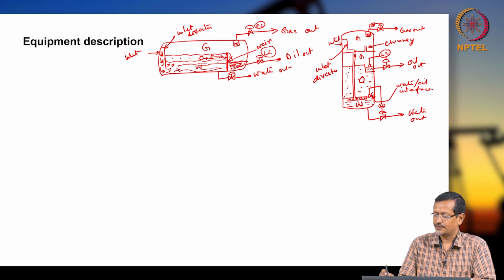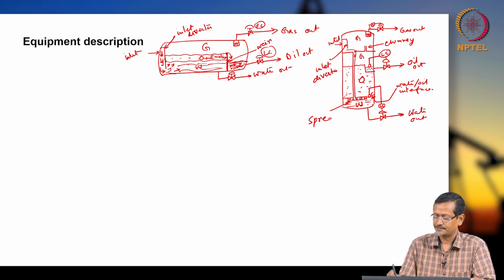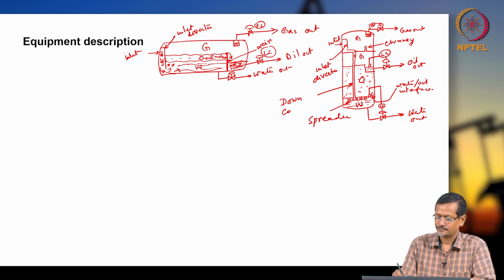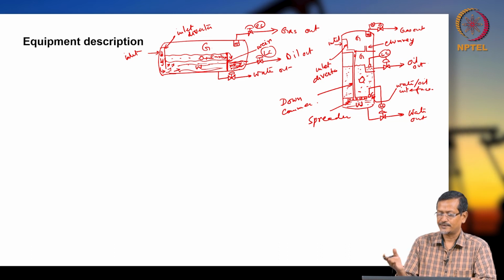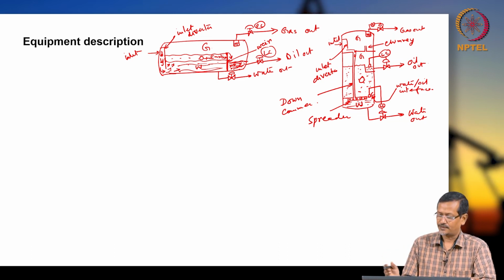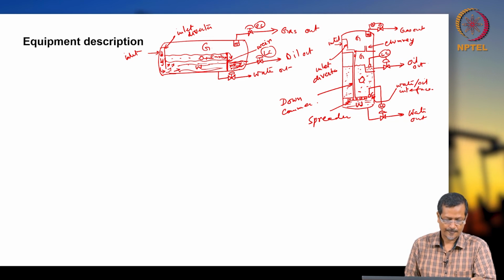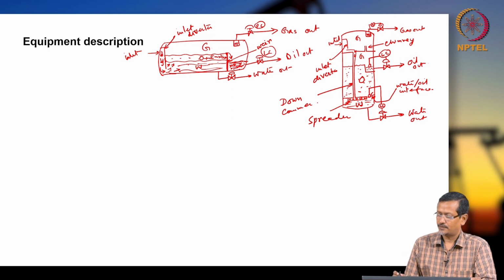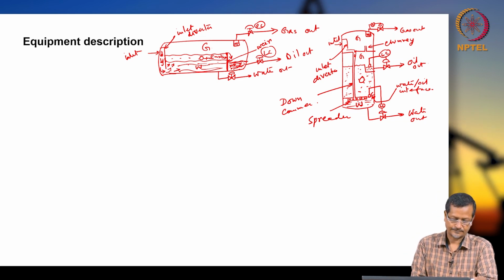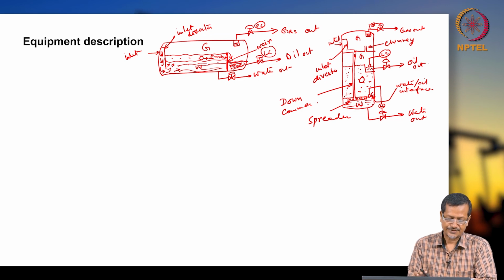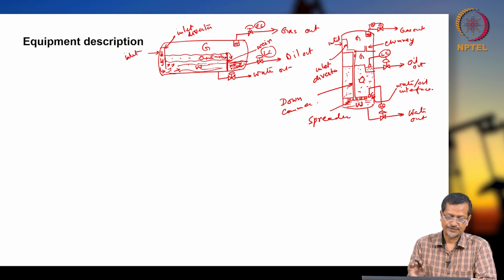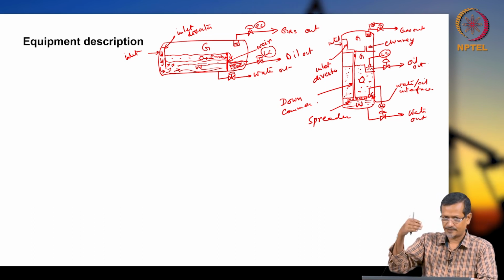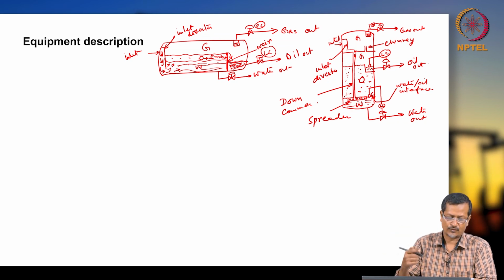Okay, so you can see this spreader. This is called the downcomer. So the downcomer will be there in a vertical separator only, and there will be a spreader because it's a long area. So the diverter changes direction. It ensures little gas or almost no gas is carried out with the liquid. Okay, the diverter will be pushing liquid down, so gas can escape.